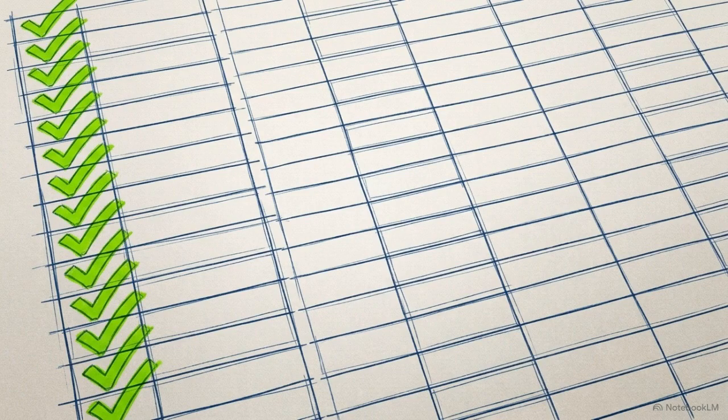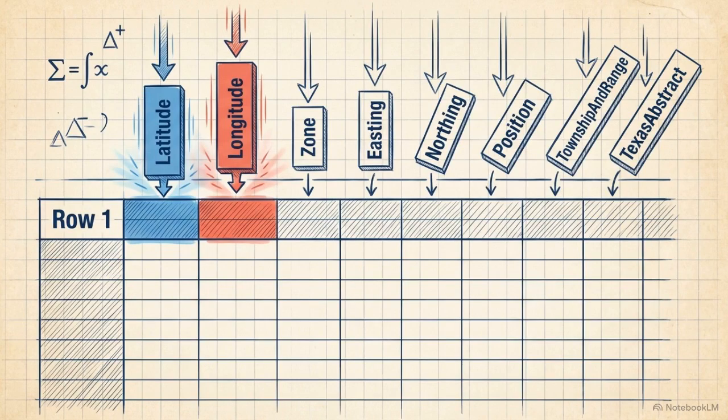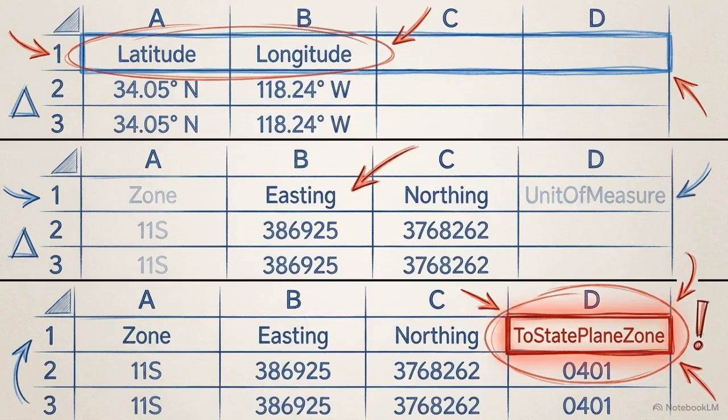Step 1 is entirely about formatting the top row of your source spreadsheet. The conversion engine relies on exact naming conventions to understand your data. If column headers don't match EarthPoint-specific names, the system cannot process the file. This standard spreadsheet layout assigns specific names to top cells. For GPS coordinates, exactly name columns latitude and longitude.